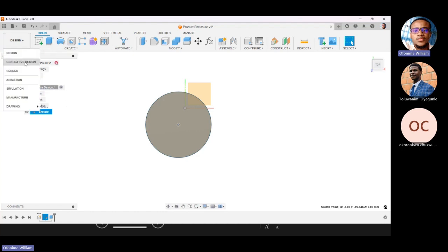So maybe you've done your design and you are now on drawing, creating a drawing file. The updates we have done by moving this will also update down to the drawing file, and mess up your animation, because even the animation you are trying to create will have everything shifted. If you're doing something on the manufacturing simulation, whatever it is, as long as it's tied to this file called enclosure design and you have moved the sketch and the geometry has readjusted, everything changes. So it is both beautiful and could be heartbreaking. I just had to point that out. So having said that, I will delete all of this and then we'll commence our design proper.